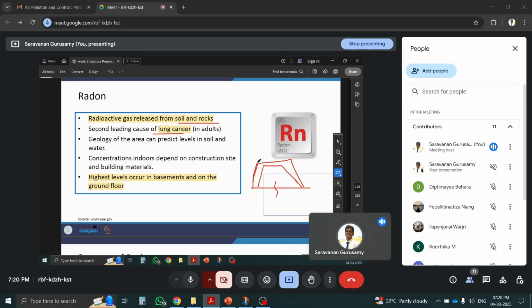Capping, in the sense they have covered it with the liner system, so that rainwater will not enter into the landfill. Also, the methane gas that is produced will not escape into the atmosphere. So they thought the pollution was prevented, but actually there is no capping at the bottom, or no liner at the bottom. An actual scientific landfill should have a proper liner system, and the waste will be there, and then we need a covering system. Then only there will not be any water intake, and gas outflow will be there. So then it will be prevented.